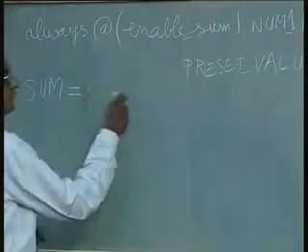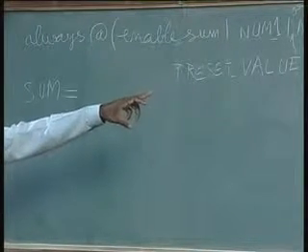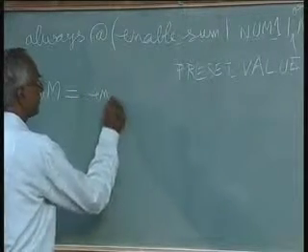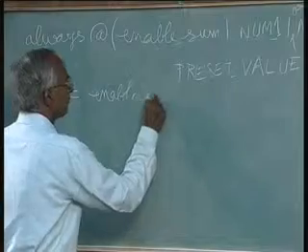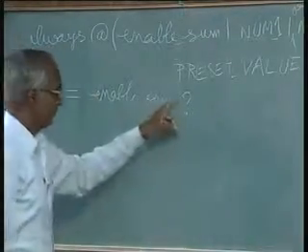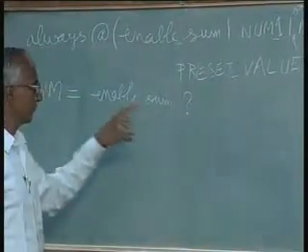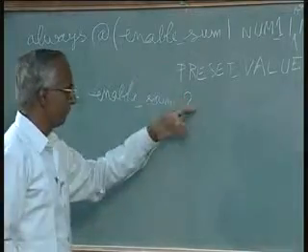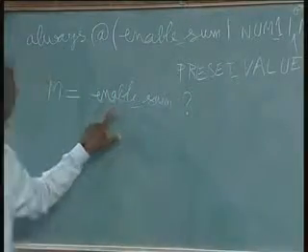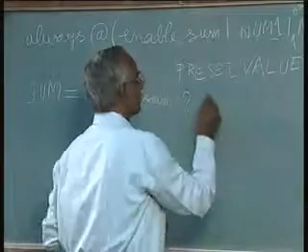So now what we want to do is we have to take enable sum into account while writing the sum. So let us say in the mux the selector control is enable underscore sum, and the mux is identified by this question mark symbol. And now what we want is, there are two inputs for the mux. So the higher order input will be put here. That's what we want here, because when enable sum is 1, we want to add the two numbers. So what we will do is, we will put that